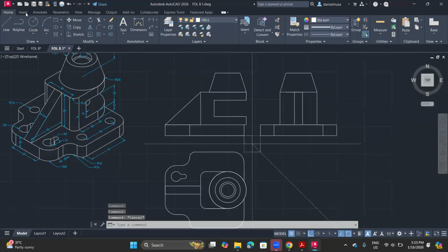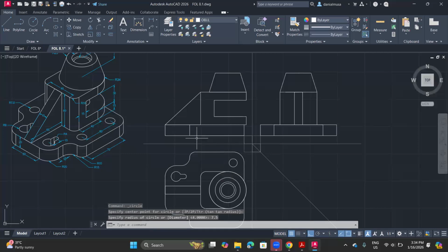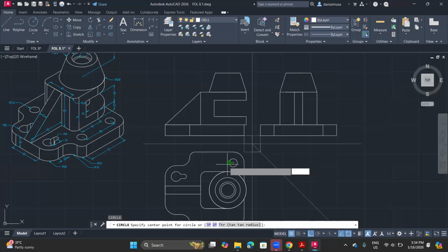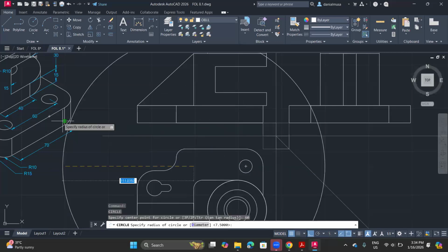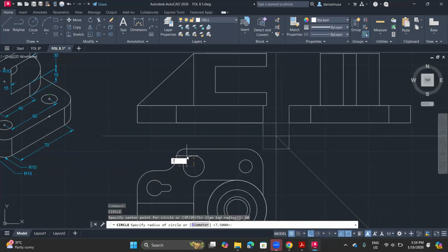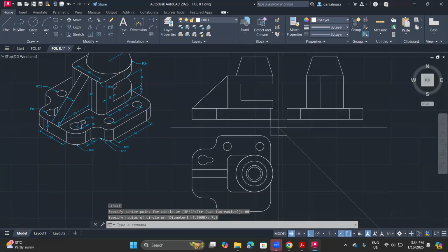And after, if we're going to draw the part here, I just make it similar to the center line here. So we use a circle here, close to here, to draw it, its radius is 7.5. And then using the same circle and the same method, just close to the center and move. We want to see the center, the green line, and insert 0. Here I say 0, and also the same, the radius 1.75. Alright, so we have completed this side.